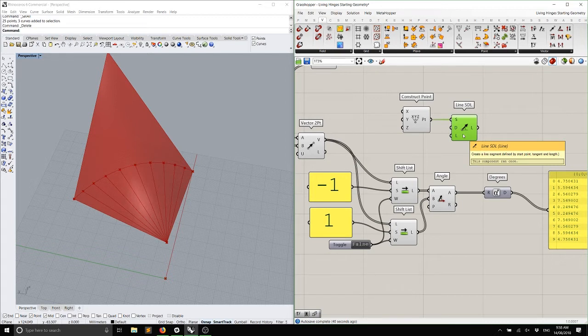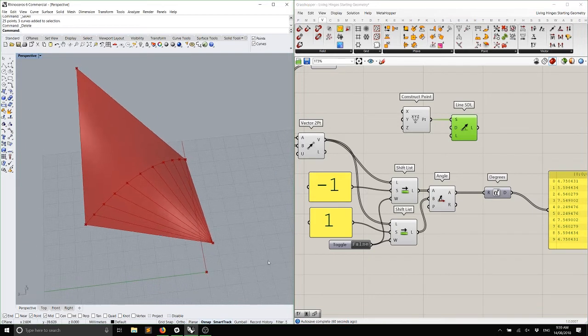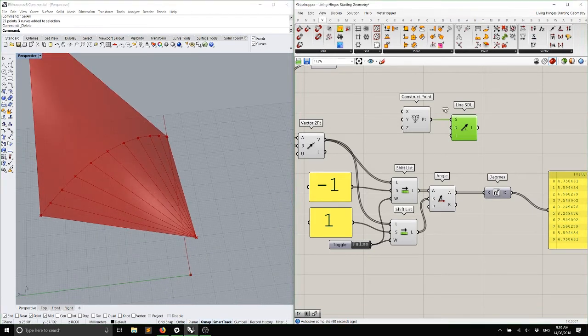And I think that's kind of a method that a lot of people use to draw lines in CAD, yeah? You have your start point, you just put your mouse in the direction that you want to go, you type in the length that you want it to be, and then it draws your line, right? Cool. And then if you want to do a 2-point line, you snap from one point to another, yeah? Okay, so what we're going to be doing is drawing lines in the x direction.